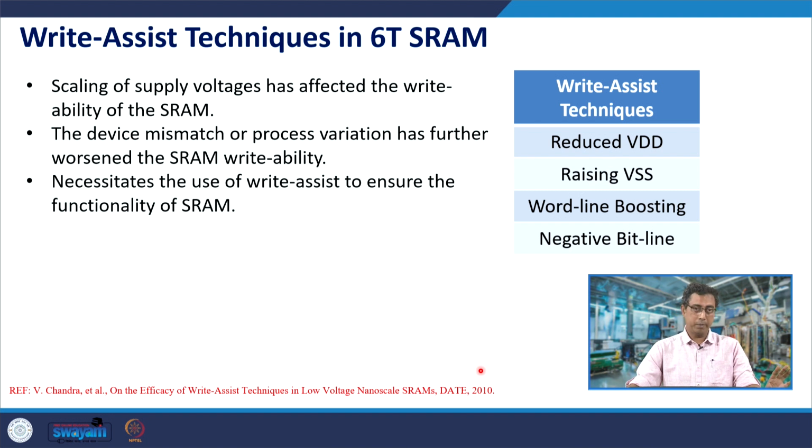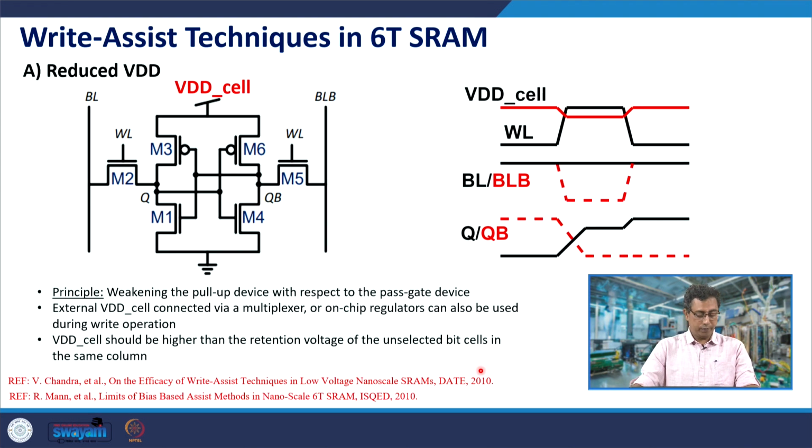So, to increase these margins and also to increase the writability, write assist circuits or write assist techniques are resorted to. We will discuss a few of these write assist techniques. One of the write assist techniques is to reduce the VDD of the SRAM cell.